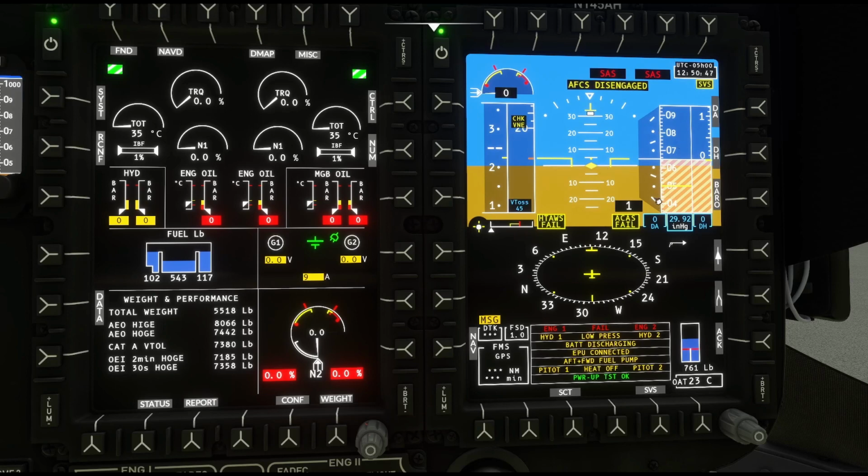So right here is your VSI, your vertical speed indication. This line will move up and down and point to 500, 1000, 1500, 2000, and then the scale will max out at 2400 up here at the top. And that's rate of climb and rate of descent.